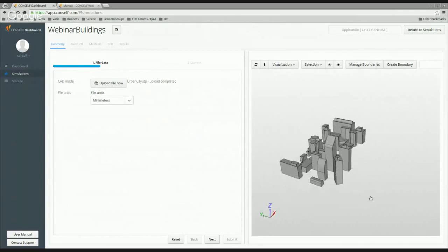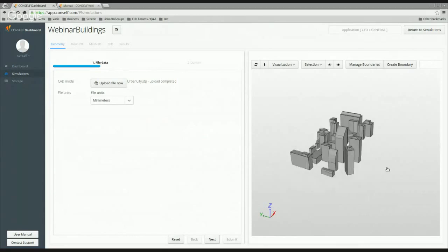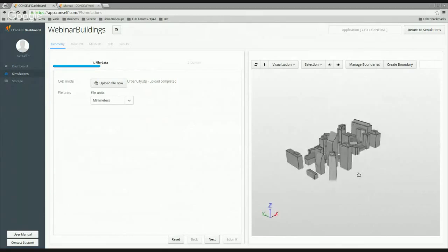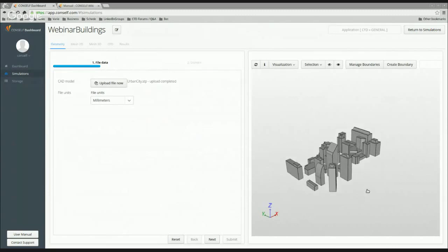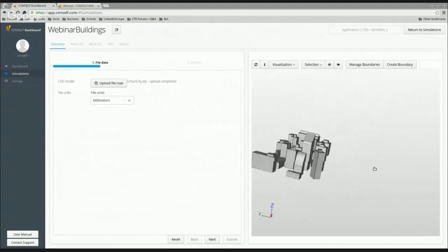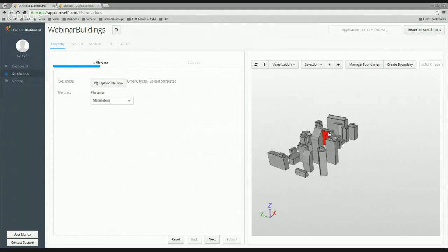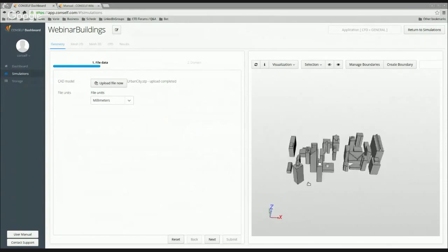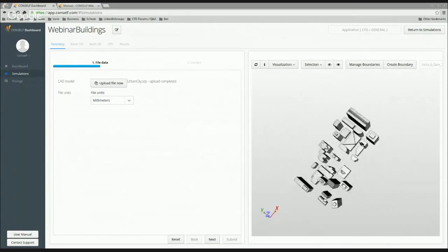This graphical window allows you to interact with the mouse. With the left button, you can rotate the geometry. With the right button, you can zoom in and zoom out. And clicking the middle mouse button, or both left and right, you can move the geometry around. In order to reset the center of rotation, you have to double click on the point you want to be the new center.